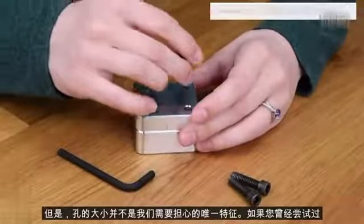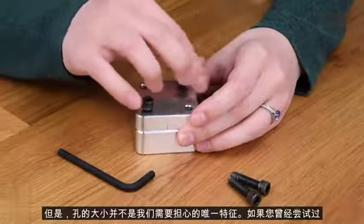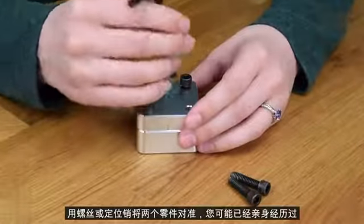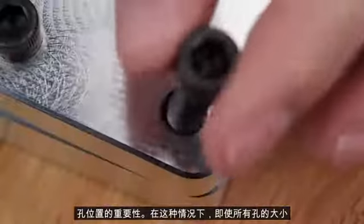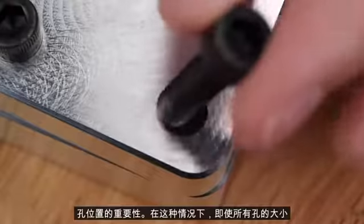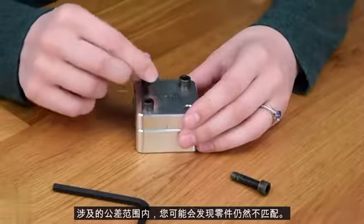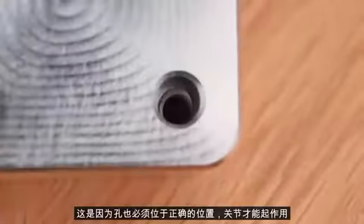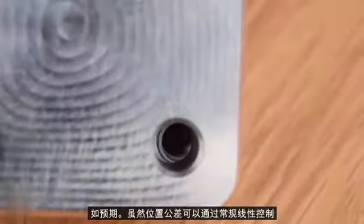But a hole's size isn't the only characteristic we need to worry about. If you've ever tried to align two parts with a pattern of screws or dowel pins, you may have encountered firsthand the importance of a hole's location. In this case, even if the sizes of all the holes involved are within tolerance, you might find that the parts still don't fit together. This is because the holes must also be in their correct locations for the joint to function as intended.